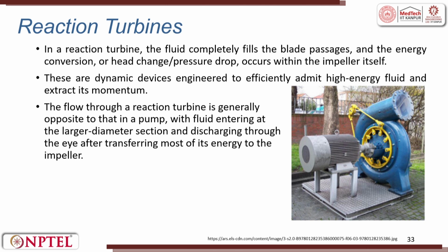The reaction turbine is a turbine in which the fluid completely fills the blade passage and the energy conversion of head changes. The pressure drop occurs within the impeller itself, right. They are dynamic devices engineered to efficiently admit the high-energy fluid and extract its momentum. High-energy fluid can be a jet of water or it can be steam. The flow through a reaction turbine is generally opposite to that of a pump, with fluid entering at a larger diameter section and discharging through an eye after transferring most of its energy to the impeller.